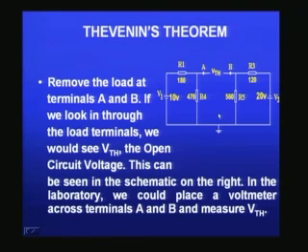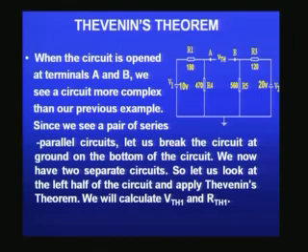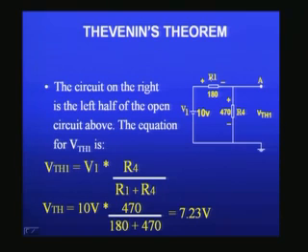So, I already mentioned to you, we will consider this in two parts, left part and the right part. So, let us look at, for example, V Thevenin 1 corresponding to the left part, V Thevenin 2 corresponding to the right part alone, considered separately, and then combine the two together. So, now I have here the left half of the circuit, and you can immediately see V Thevenin can be obtained because there are only two resistors, they are forming a potential divider. Therefore, I can calculate the V Thevenin corresponding to this simple circuit on the left side.